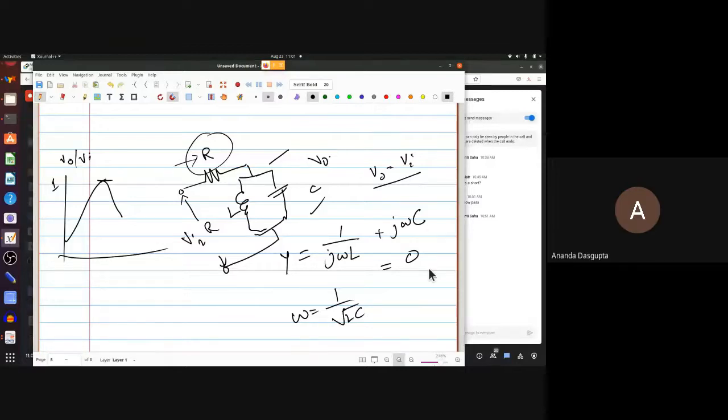That's exactly the problem with trying to put results from one circuit onto another. You need a small resistance in a series LCR circuit for sharp resonance. In a parallel LCR circuit, as I just said, the job of the R is to bring the voltage down, right? As you move away from the resonance, the voltage has to come down. And if the R is large, it's going to come down more. Simple. It's large R which gives you a good resonance. Small R doesn't. Small R gives you a good resonance for a series LCR circuit.